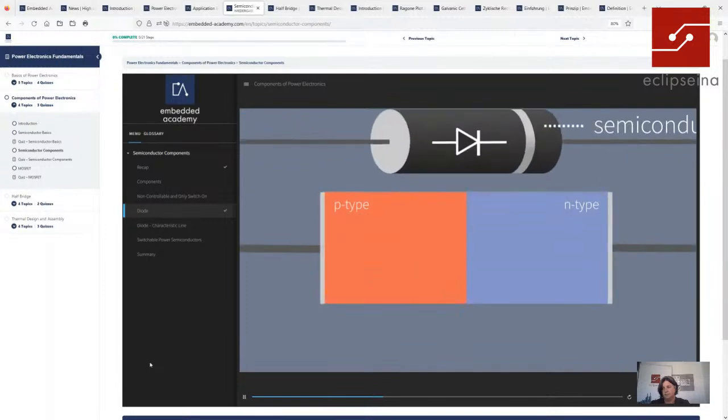It consists of two areas, P-type and N-type doped. These regions are created by adding other materials in each case. P-type means that there are too few electrons in total. The connection layer is called anode. N-type means that there are too many electrons. The connection is called cathode.